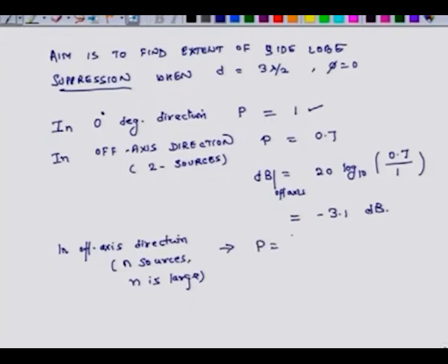we measured, it was approximately 0.2. So, in decibels off axis, that is equal to 20 log of 10, 0.2 over 1, and that works out to be minus 14 dB.